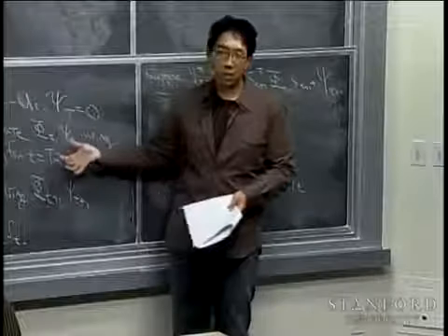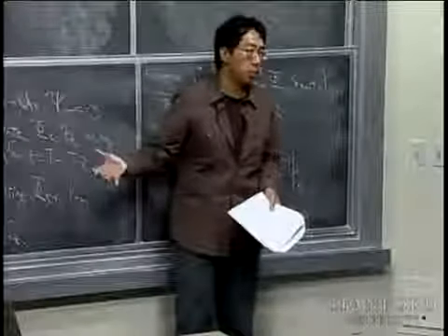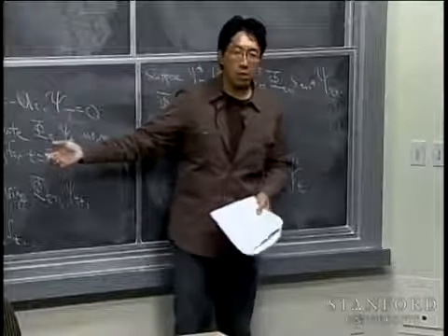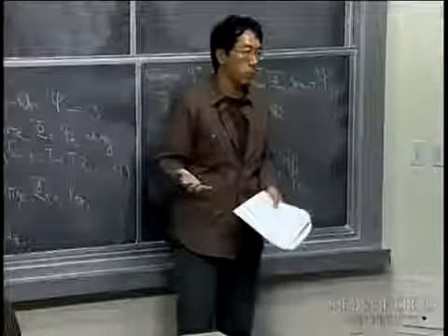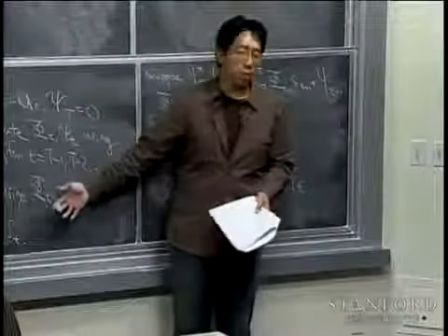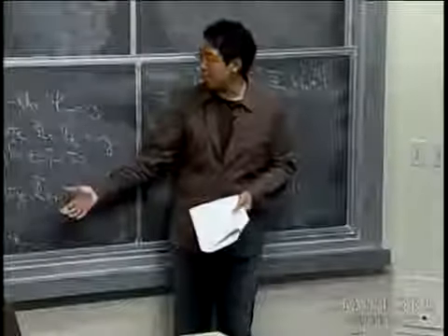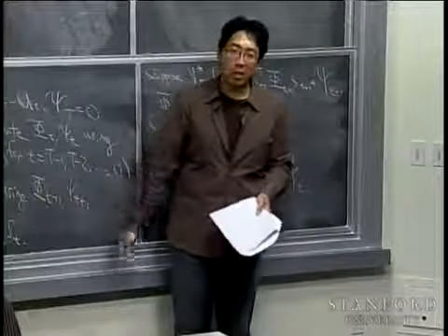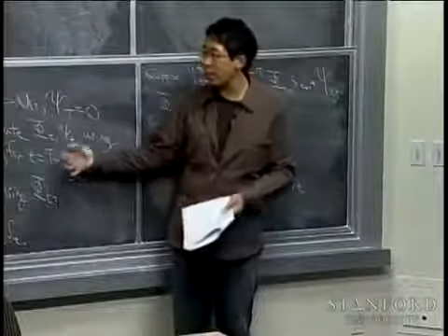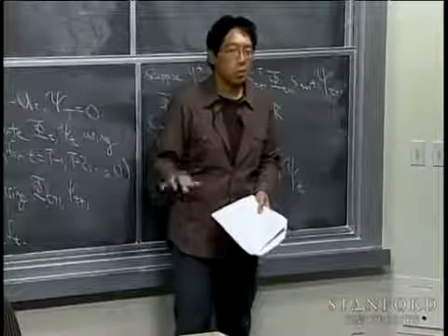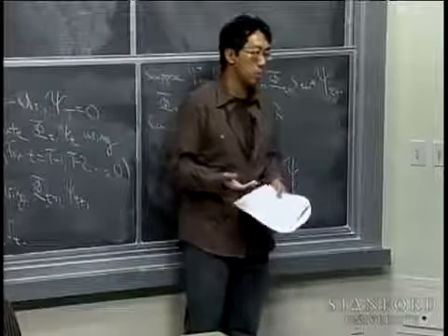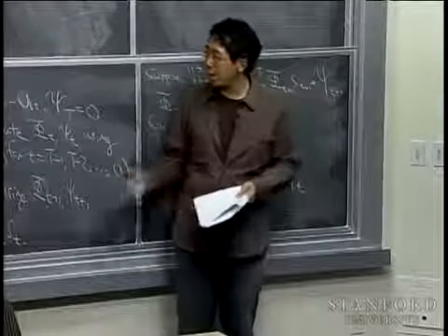And so the computation of this algorithm scales only polynomially in terms of the number of state variables, like the cube. Whereas in the curse of dimensionality problems, with discretization, we had algorithms that would scale exponentially in the dimension of the problem. Whereas LQR scales only like the cube of the dimension of the problem. And so this is easily applied even to problems with very large state spaces. We often apply variations of this algorithm to a significant subset of the things we do on our autonomous helicopter, which has high dimensional state spaces, like 12 or higher dimensions. And this has worked very well for that.